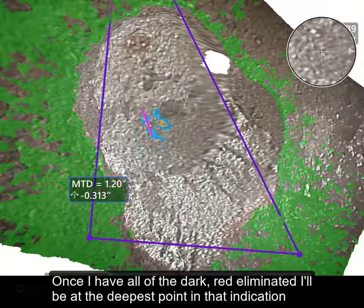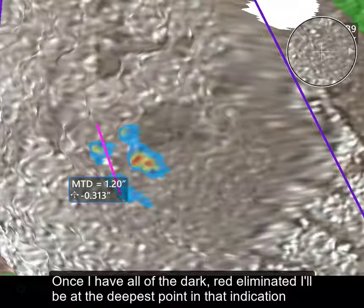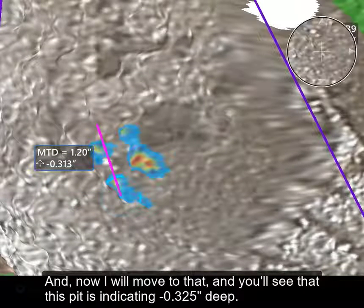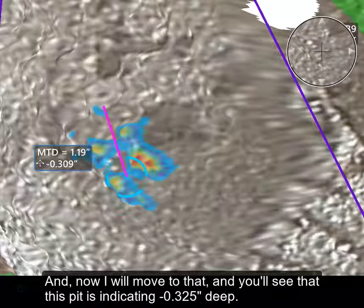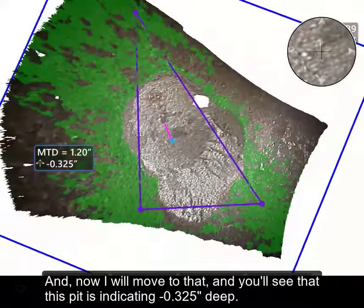Once I have all of the dark red eliminated, I'll be at the deepest point in that indication. And now I will move to that, and you'll see that this pit is indicating 325 thousandths of an inch deep.